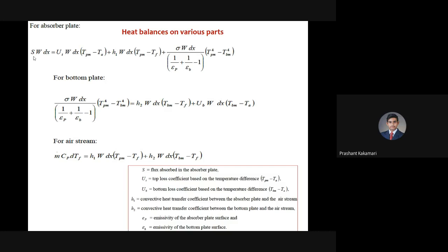But here we are focusing more on how the equations are going to change with respect to the flat plate collector and the air heaters, because here we are not considering the plate as a fin. That you have to keep in mind. We are not considering the absorber plate as a fin here, because it is not acting as an extended surface for a tube. It is a complete surface, and here we don't have the pitch of the tubes or the width between the tubes, and we don't have the diameter of the tubes also, as we considered in the liquid flat plate collectors. So neglecting those terms, we need to focus on what the effective heat removal factor, the flow factor, or the efficiency factor will be. I hope you are getting the point.